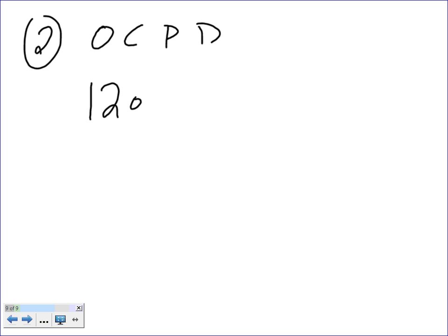Number 2. Let's do number 2, guys. What was number 2? Ungrounded conductors. Overcurrent protection device. So what was the size we have? 1200 amps. We're going to take this one to 240.6 from NEC. Do we have 1200? Yeah. Now, should I go for the next size, 1600, Spencer, right? Should I go 6?